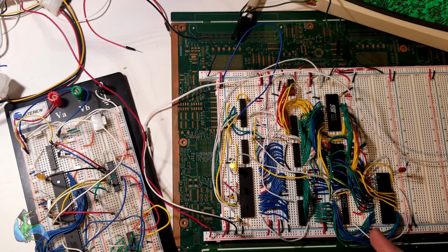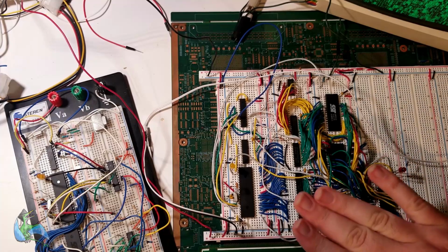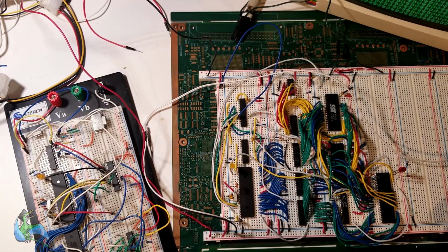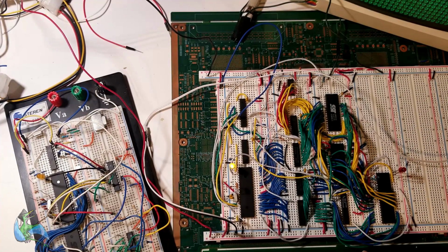Now in this mode, it actually switches to a memory map in which there's 44K of RAM at the bottom of the memory map, and then font ROM is at the 44K mark, which is very similar to where I think a VIC-20 keeps it. Or Commodore 64, I don't remember.